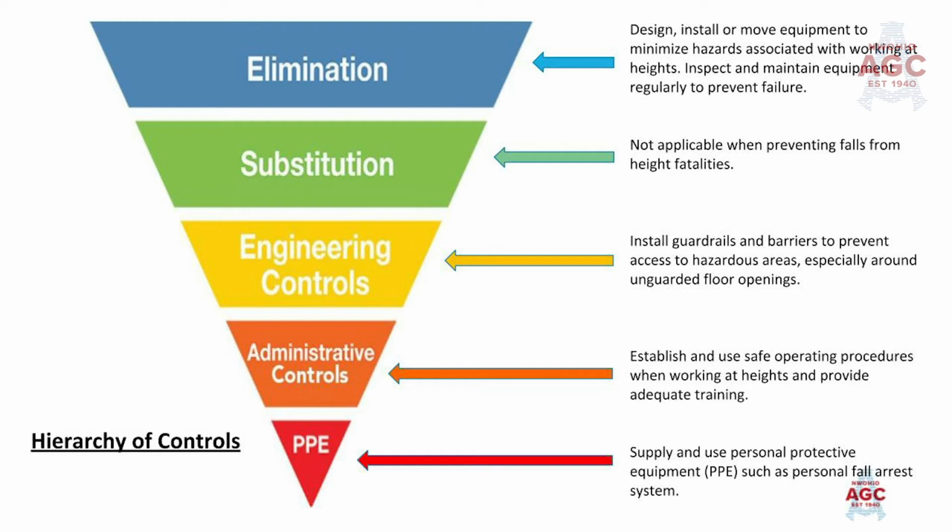Eliminating the hazards. How do we eliminate the hazards in fall protection? Instead of workers erecting scaffolding with no fall protection, erectors could erect scaffold on the ground and lift sections up to the erectors who are waiting behind guardrails of previously erected scaffold. Or lights on towers. Can we lower the lights to change the bulb instead of a worker climbing to change the bulb? In fall protection, substitution is not available.